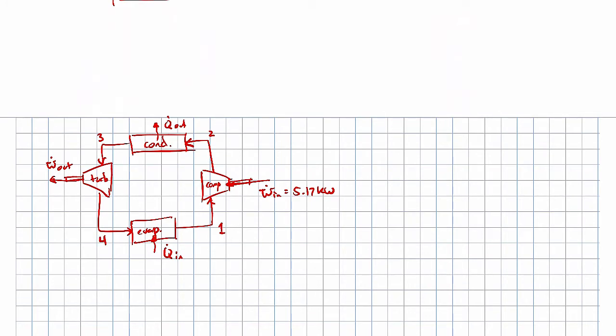Okay, so this will be our new system, our new cycle that we're going to investigate, because we're replacing the expansion valve with the turbine. And the reason we're considering this is because we can generate some power out of the turbine, that might help reduce the net amount of work that we have to put in. So we take some of that power and just put it right back into the compressor, and so that would make our whole cycle a little more efficient, right?